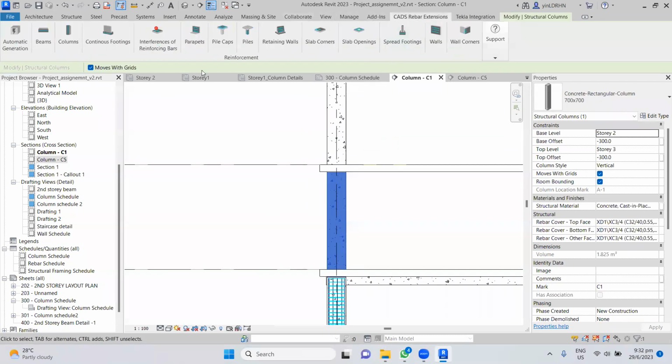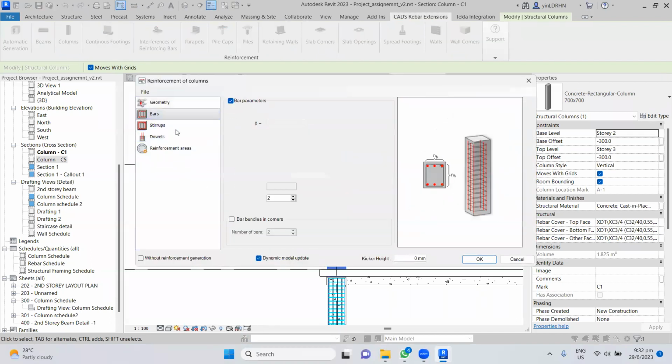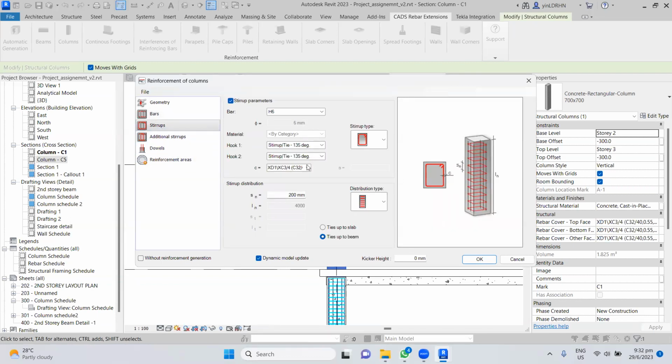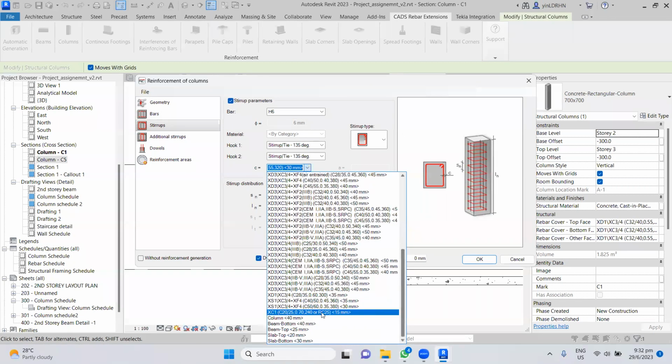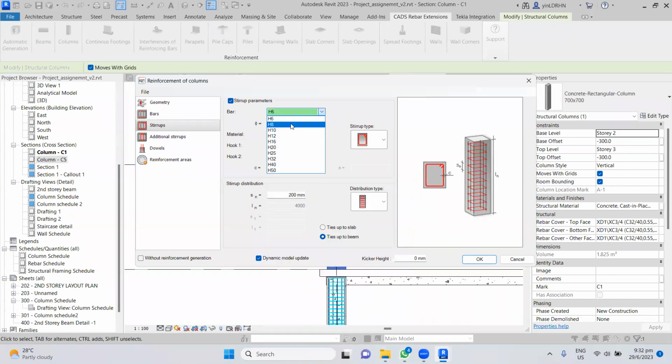Okay, I had the same rebar here, right? Okay, vertical bars is 20, right? It's asking the top, do you want any hook or not? I don't need a hook top, so it's none. Bottom, do we need any hook? No, I don't need any hook. So it's 5 rebar, right? Stirrup, I set up the cover first. Okay. H8, this type, okay. Uniform is 150 spacing.